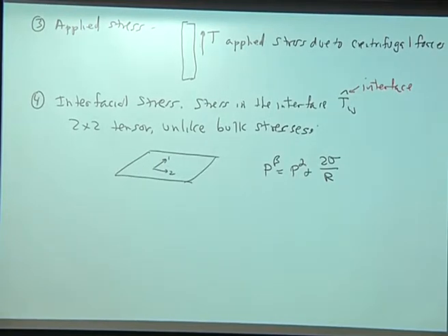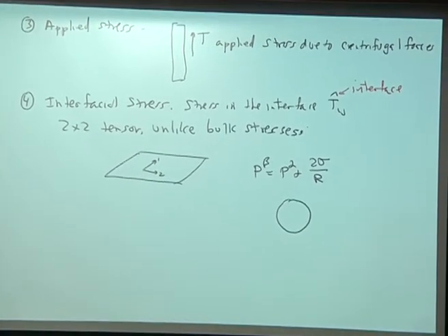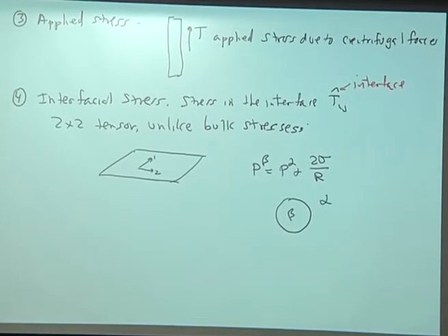This is the Laplace equation, and what it says is if you have a liquid of phase beta in a fluid of phase alpha, and you have a surface tension or surface energy, it generates a pressure. And so you want to think of the sigma or the surface tension like a rubber membrane that's surrounding this liquid and is pushing under pressure, right?